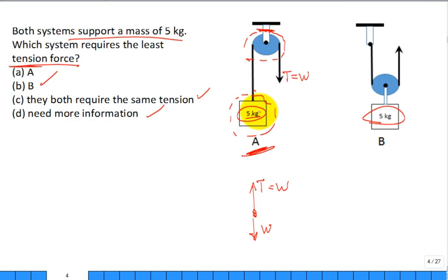Okay? Let's do this one. Should I do a free body diagram around here? Sure. Then this is a support going to the middle of that pulley, and we know it's the weight coming down. We do a free body diagram around this pulley, and so now we knew that either the shaft or the cable holding that is coming down with the weight W. But I have 2 cables coming up, do I not? You cut right there and cut right there. And this is a cable going around a pulley. If it's in tension T, it's pulling up with tension T, pulling up with tension T. True or false?